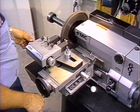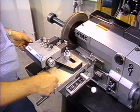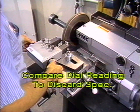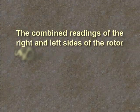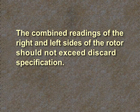Retract the bits from the rotor and turn the cross-slide wheel until the bits are over the deepest groove in the rotor. Turn the depth of cut dial until the bit cuts a continuous groove in the rotor. Read the micrometer dial and compare this reading with discard specification. The combined or total readings on both sides of the rotor will tell you if the rotor can be cut to the deepest groove and still be within discard specification.